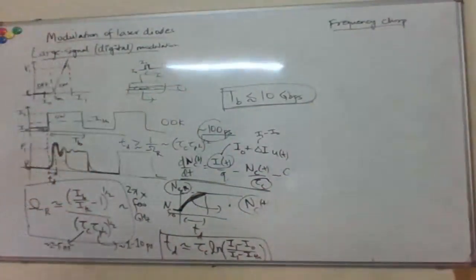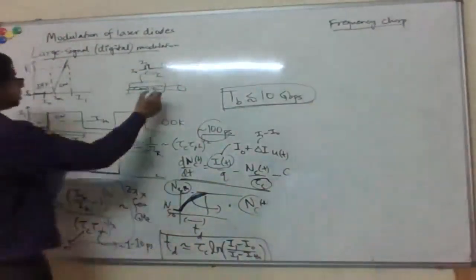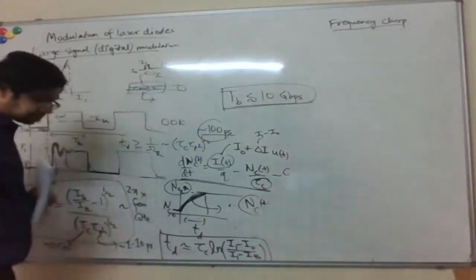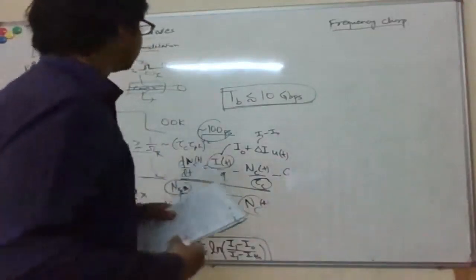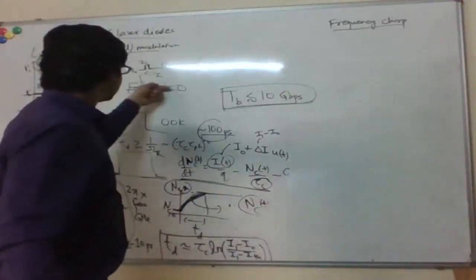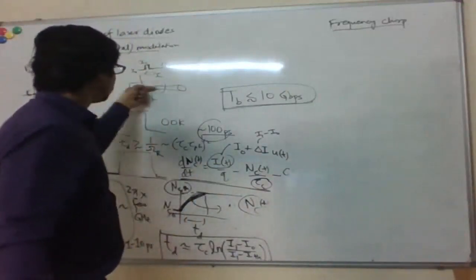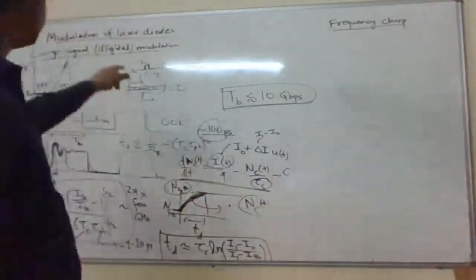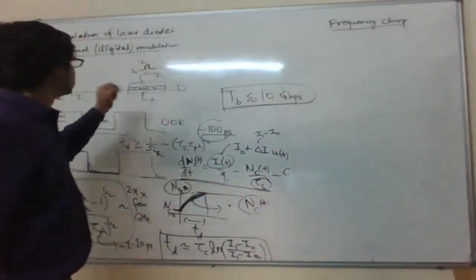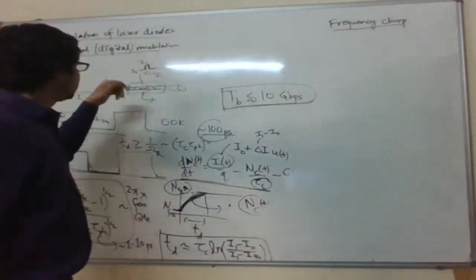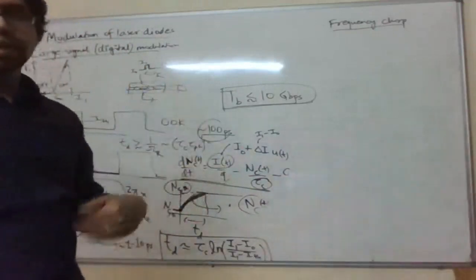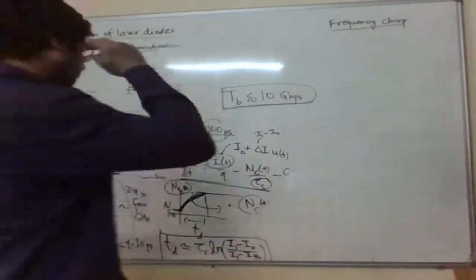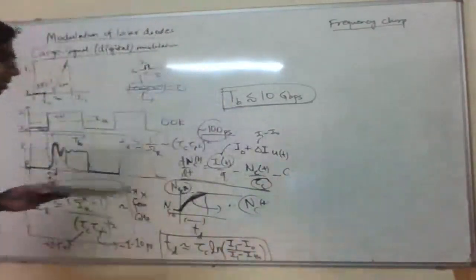Okay, and basically you know that you're forming some sort of mode in the laser cavity here, right? And you can imagine that what this is doing is changing the effective index or the phase acquired by this mode traveling across the cavity. And so now if you have a time dependent current, the refractive index becomes time dependent, and so the phase acquired becomes time dependent. And a time dependent phase is basically frequency, right? So that's how you get this frequency chirp.